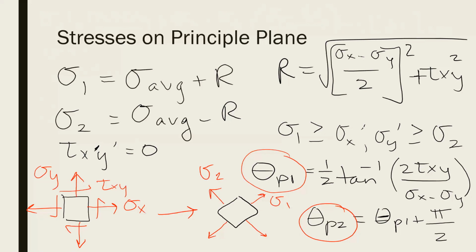So that sigma average isn't like force over area? No. We do talk about average stress when we're talking about calculating these stress components. When I talked about sigma average previously, I was saying, for example, if you have an axially loaded member, like we pull on the ends of this, that would be our force divided by the cross-sectional area of this object. That gives you an average stress component. But now when I say average, I'm saying the average of these 2 stress components that we've already calculated.